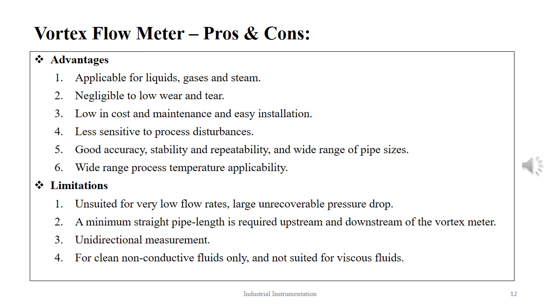The few limitations are, however, they are unsuited for very low flow rates and for large unrecoverable pressure drop. A minimum straight pipe length is required for both upstream and downstream of the vortex meter. They can only measure unidirectional flow, and they are applicable only for clean non-conductive fluids and not suited for viscous fluids.